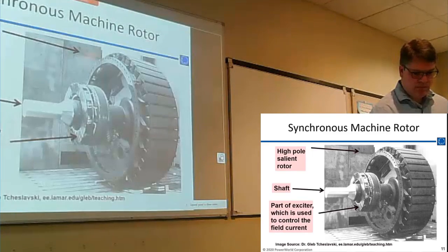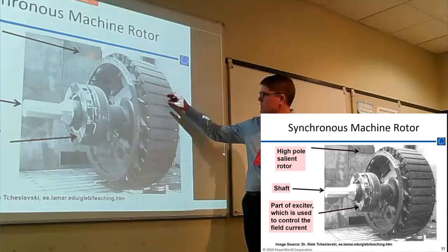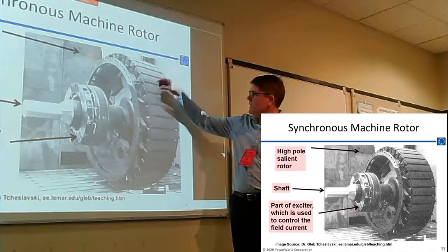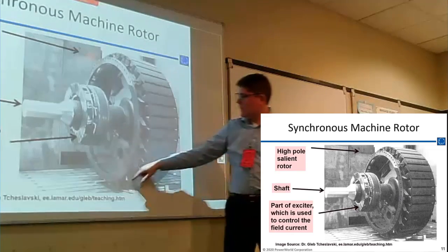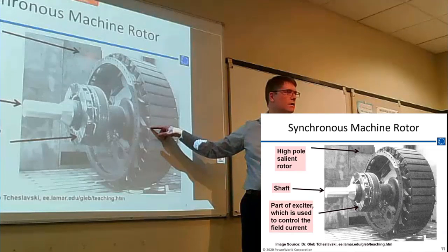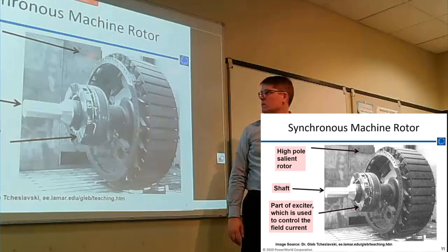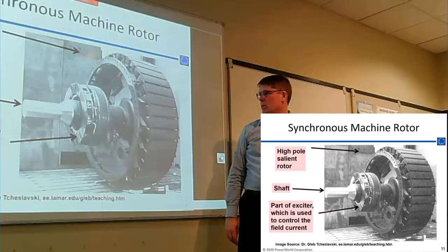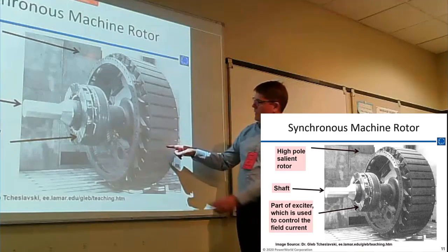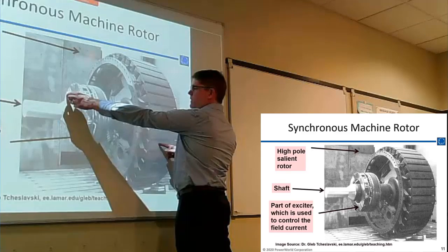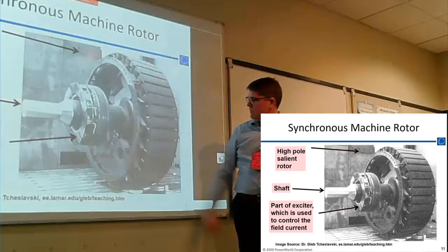This is a picture of a rotor. This would be more salient. Actually, I'm learning things. So these are the pole pieces that are getting put on there. And clearly there are a lot. If I were to count all these and divide by 3, actually divide by 6, that's the number of poles. So there's a lot of pieces on there. This is probably a 12-pole rotor. Actually, each pole would be a pole, because it's the DC, right? It's the DC. Well, correct, but there's one on here and one over here, that's a pole pair. Oh, you're right, pole pairs, yes. So you just count them all. Wow, so that's probably like a 60-pole machine, something like that.